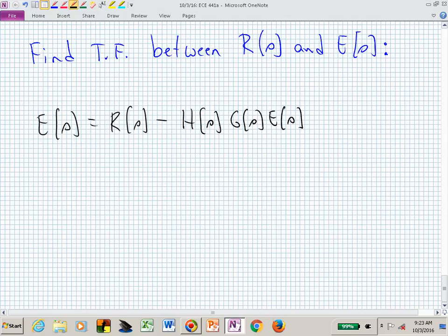But does everyone feel comfortable with that expression? And you see where that originates from the block diagram. And we can now, by combining, and typically since H and G are scalar transfer functions, they're not matrices, they can be interchanged, they commute. So it's just more natural to say GH than HG. So GH is easier for me to say than HG.